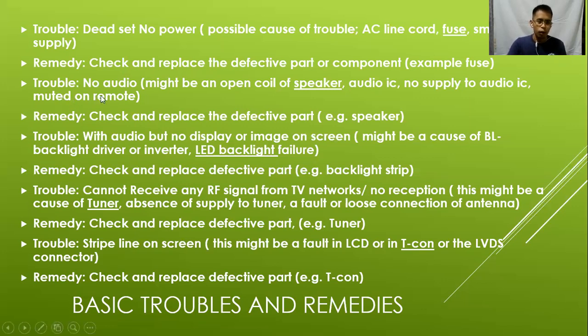Okay, another trouble is no audio. So this might be an open coil of a speaker or a defective or busted speaker. Might be a cause of audio IC or there is no supply to audio IC or sometimes it is an error from the user because the TV might be muted on remote control. So remedy, check and replace the defective part.